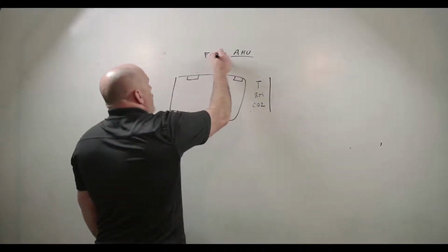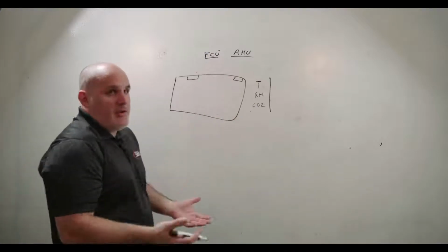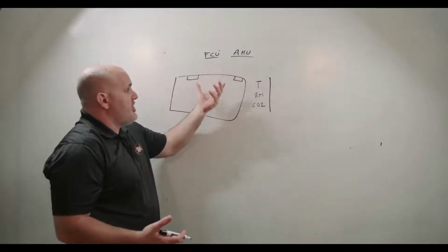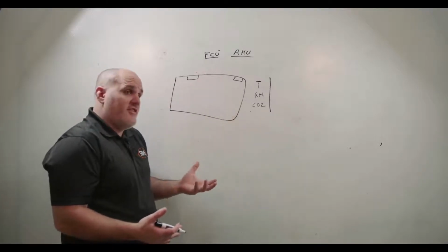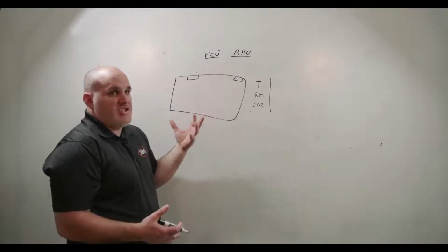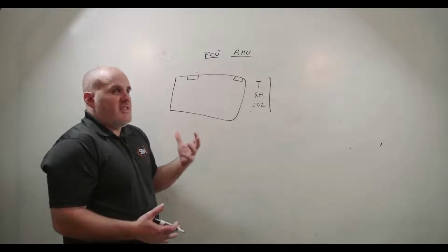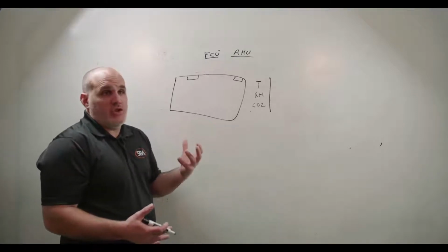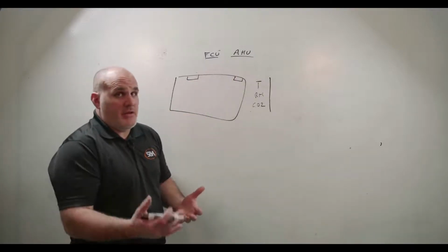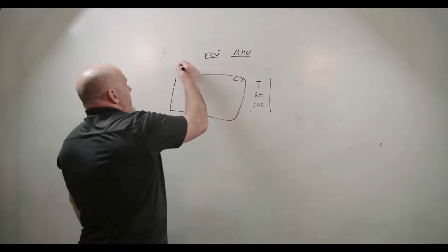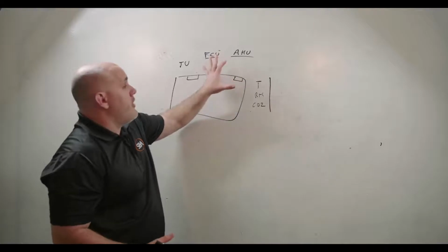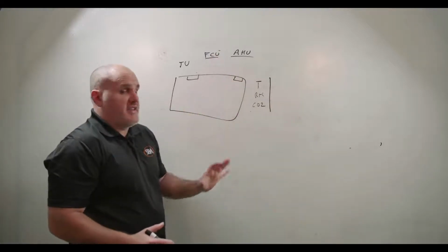Something like a fan coil unit, which you'd maybe see in a data closet, is a self-contained unit. It's usually in the space itself, either a vertical or horizontal stacked fan coil unit, and those tend to serve interior parts of the building that have high potential loads but don't necessarily justify a dedicated air handling unit or rooftop unit. And then we have a terminal unit, a VAV box, typically in conjunction with an air handler. Those are our three ways of getting airflow into the space.